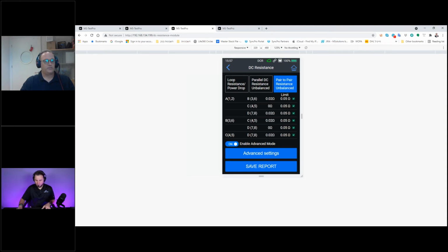and so on. You need to remember you have 4 of those, and the receiver side must get all of the signals at the same time. There is a small jitter or skew which is allowed, but it's very small. The bigger difference that you will see here means that the quality of the cable is lower, and it will affect the communication. If it's a LAN, you will get a retransmission. If it's HDBaseT, you will get loss of pixels, and so on. So this is actually reflecting the differentiation between the twisted pairs.